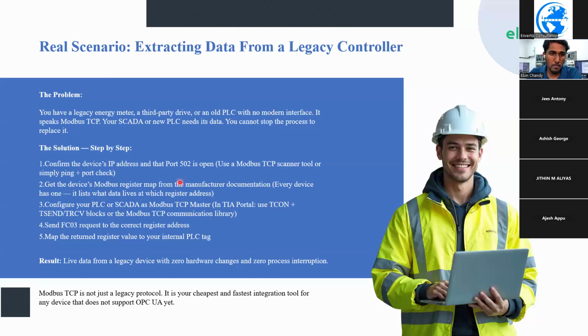In the PLC, you will be having different libraries. For Siemens PLC, we have the MB Modbus master block and the MB client block. These blocks we can configure for serial or Modbus TCP applications. Like that, we can integrate the existing system to a new PLC system.